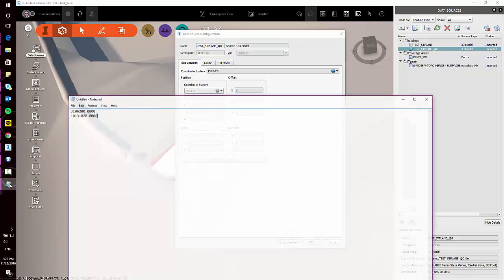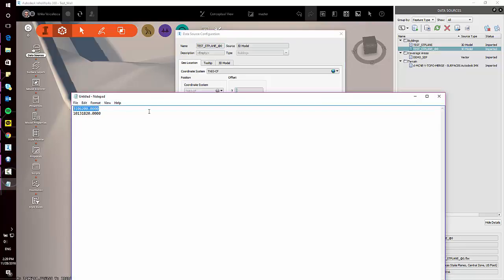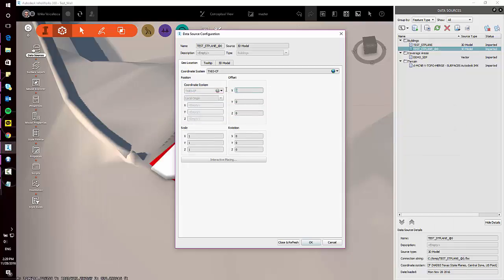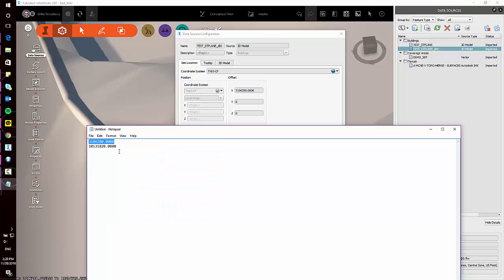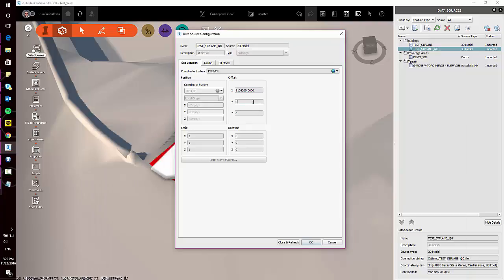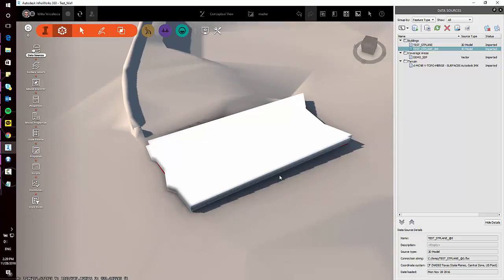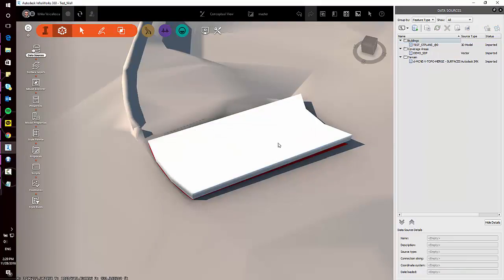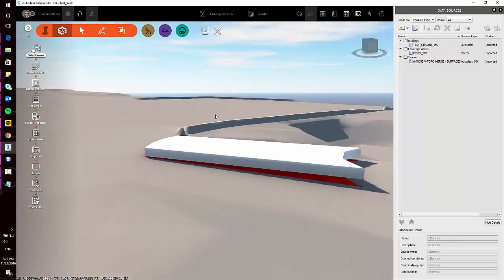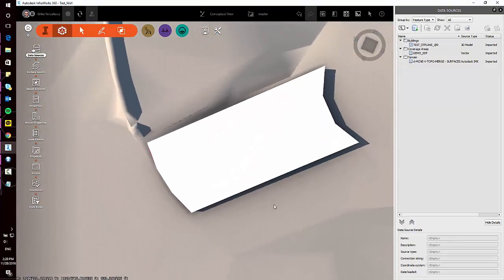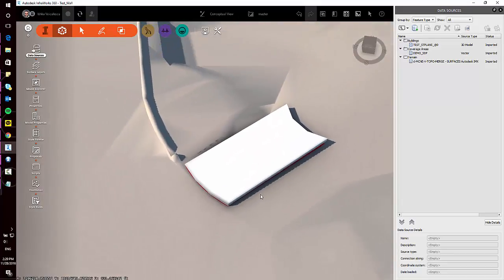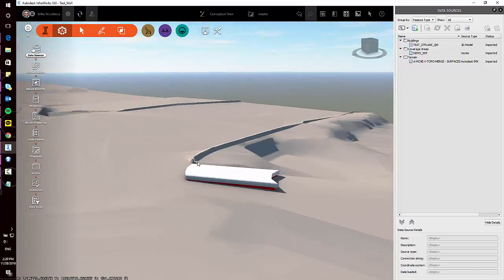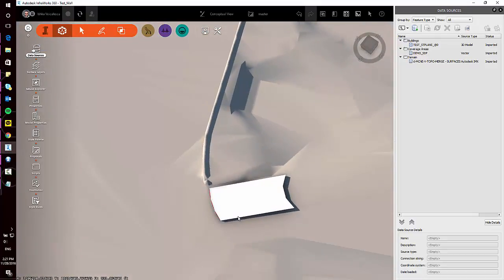So right in there, we're gonna go and look for the notepad file, look for the x and y, paste it in there, look for the y, paste it in there, and we're gonna do here close and refresh. Again, the object is placed in here. We're gonna get rid of the old object, remove, click yes, and you can see the object looks in the right place, and we had the QC for us by using the red outline. I guess it can be improved on the tessellation, but it's pretty good, what we have right now. So you can use this workflow for any objects.